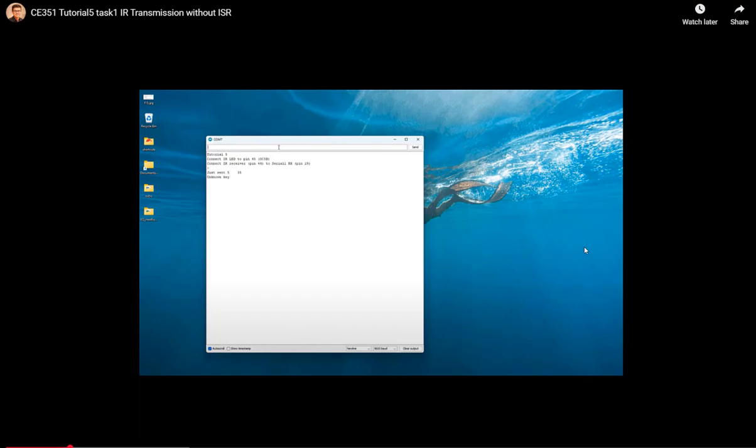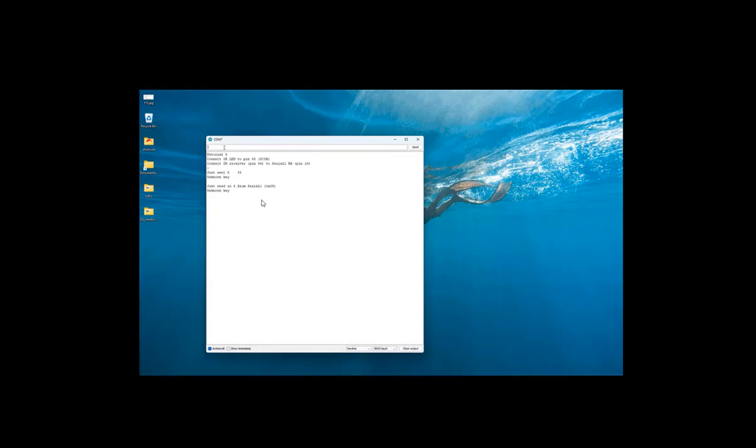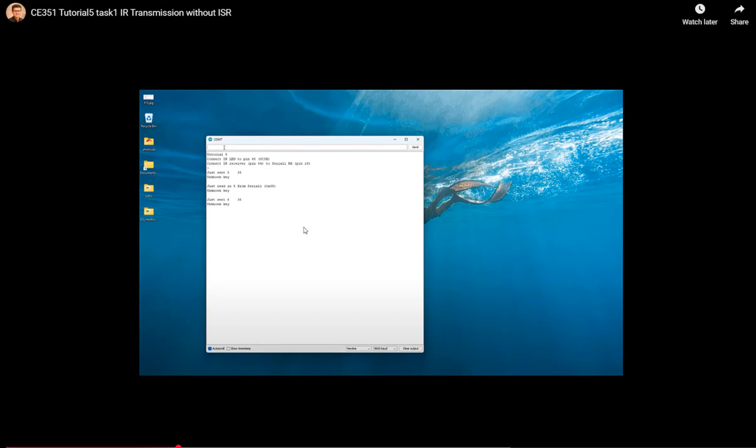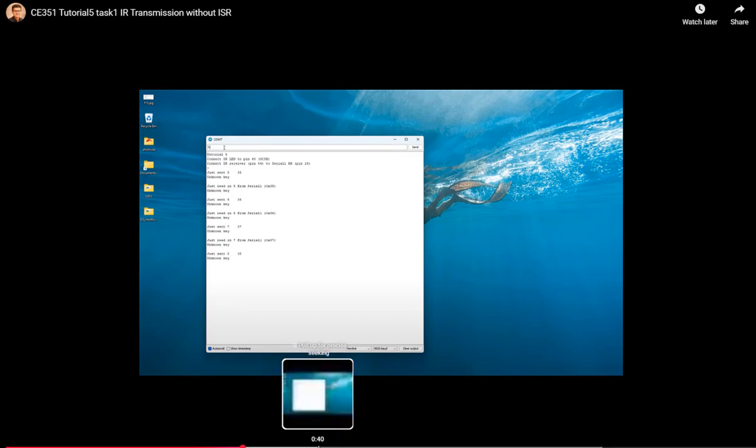5 was just sent, and so 35 here is the hex number of the ASCII code of 5. And I do another, so I'm going to resave it, press R here and enter. So 5 was just received by serial 1. Okay, and then do S one more time. 6 was sent, and R receive a 6, send a 7, receive a 7, send a 8, receive 8.